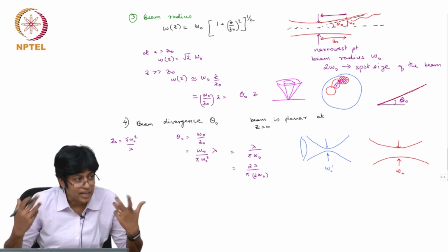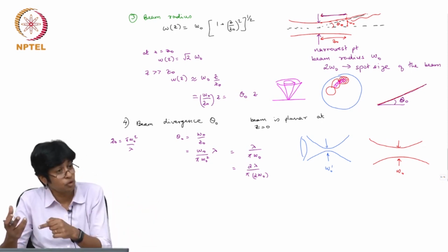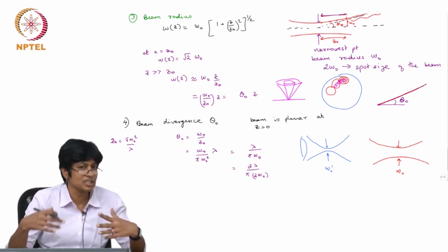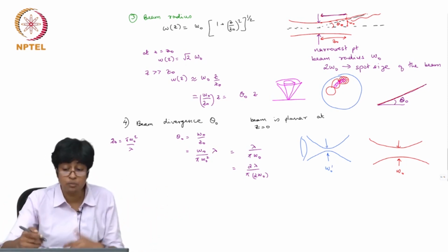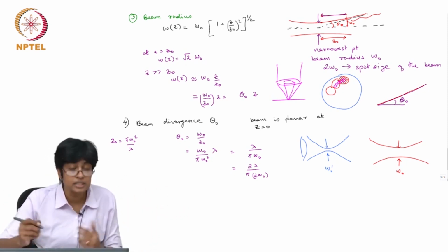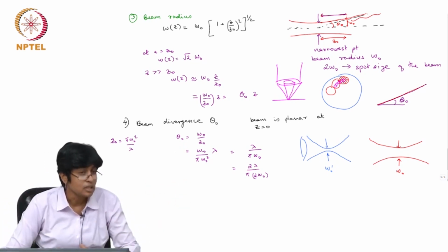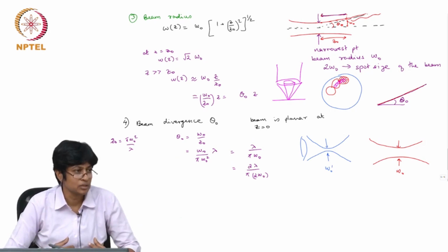So that is a trade-off that you would have to work out. If I make the focusing this small, it means the beam is larger because the divergence is larger. And the optics I need, say I want to make it parallel, the optics to control that larger divergence, maybe I need more power. So I have all these different parameters I'll have to take into account.